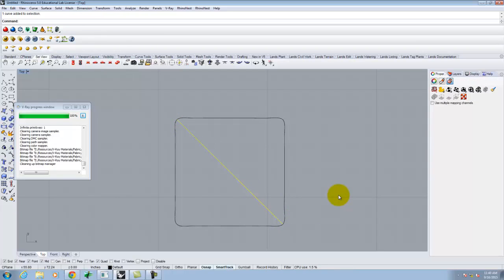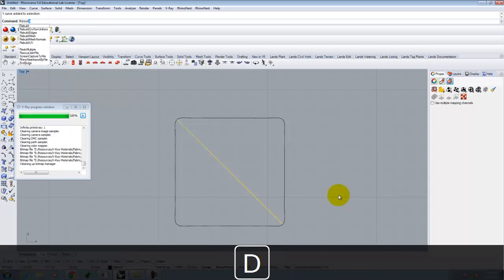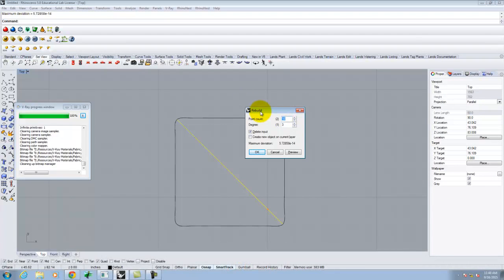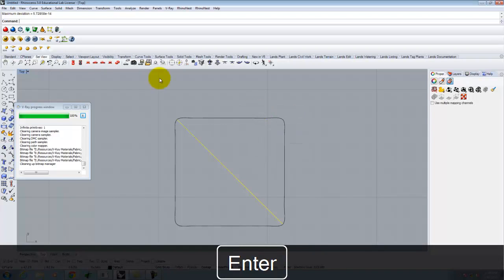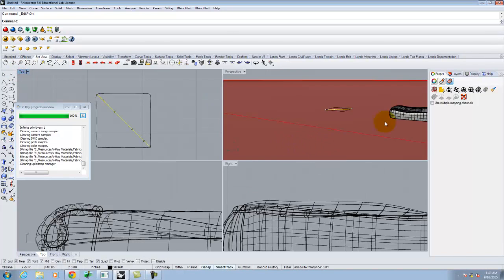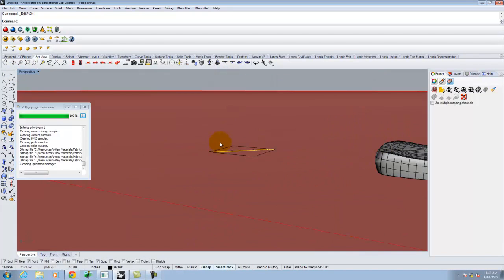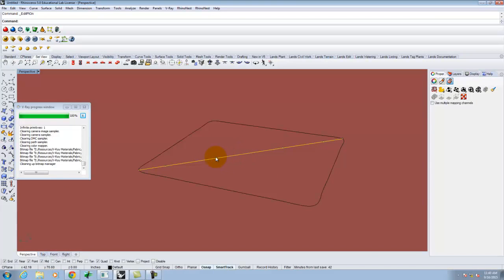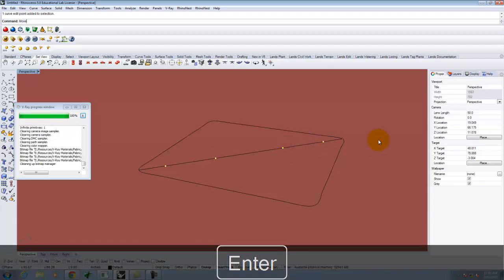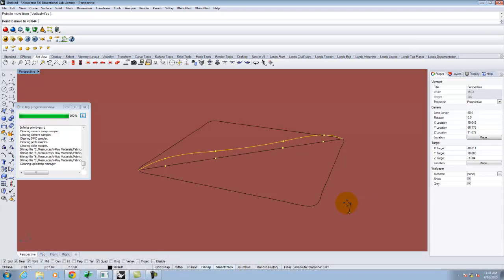And let me go ahead and rebuild this. I'm going to start it rather simple. We'll go maybe, let's go 6 and see. All right, not bad. What I want to do is look at it in its perspective view, because it's going to be really hard to see this if I don't. And we'll move all 4 of the points up a bit. There. Move, V for vertical, or again, you could use the gumball. And we'll push this up.